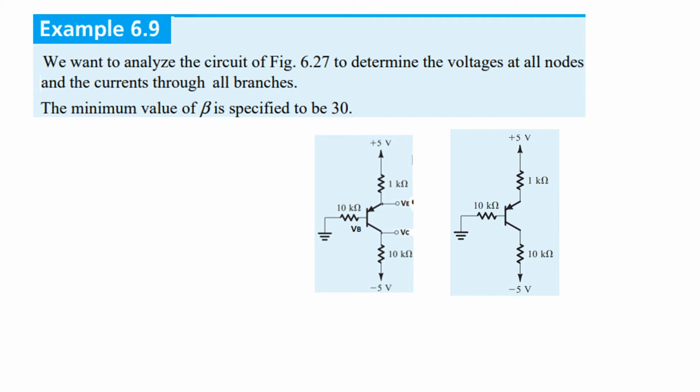First of all, I have marked the voltages VE, VC, and VB here, and then we'll keep this circuit in mind. It is a PNP, with the emitter junction forward biased, and the others we don't know whether they are forward or not. Depending on these, we can say whether the transistor is in saturation or active mode.